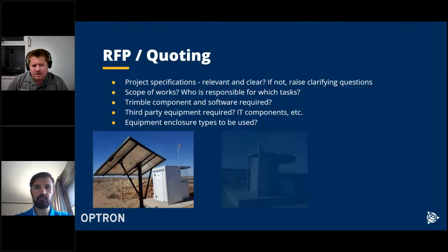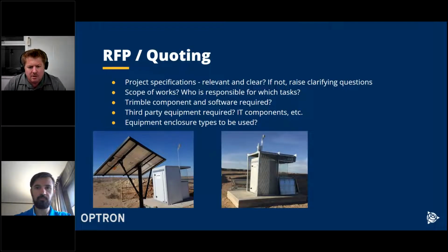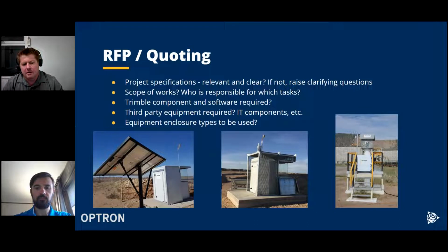If there is blasting activity, we can install the same cabin, but then we can actually build a blast cage around it, which can be closed up when they do blasting and then opened up again when it's safe to do so. And then also, if we don't need such a big enclosure, we can just build a small enclosure that sits around the total station just to protect it. Then there's a stainless steel cabinet that houses all the electronics.